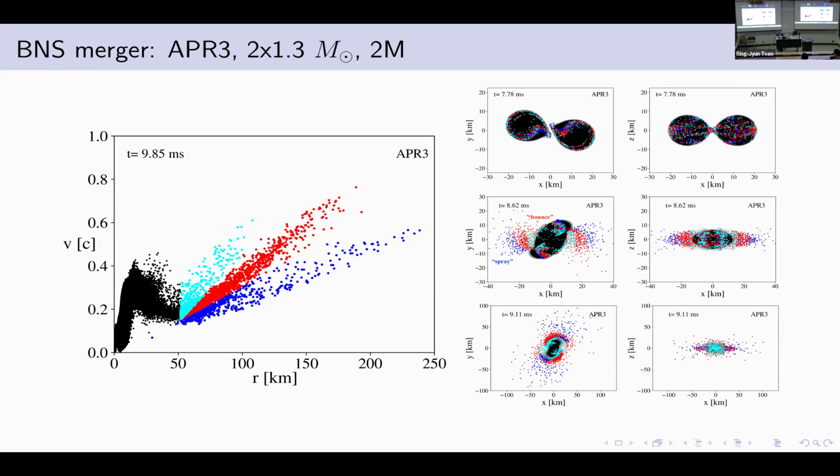The question is how we can keep the same number of neighbors for particles that are moving out here. Yes, we have to increase the smoothing length. But if you increase it in such a way that it starts touching the red particles, then you're going to get an artificial gradient of the kernel, a highly inhomogeneous distribution of particles within the kernel.